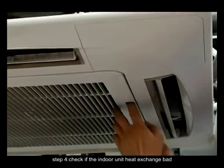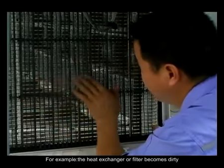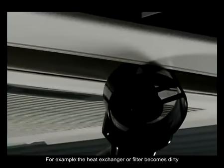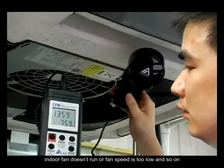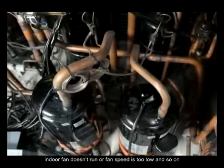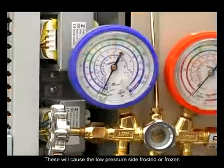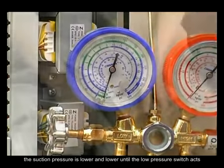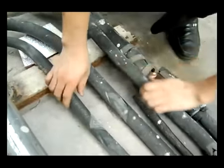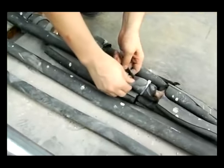Step 4. Check if the indoor unit heat exchange is bad. For example, the heat exchanger or filter becomes dirty, resistance of the air outlet is too big, the indoor fan doesn't run, or fan speed is too low, and so on. These will cause the low pressure side to be frosted or frozen. The suction pressure gets lower and lower until the low pressure switch acts. If it exists, please check and exclude the malfunction.